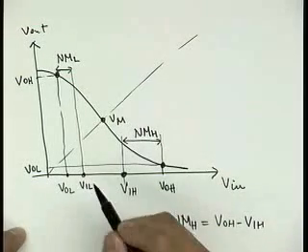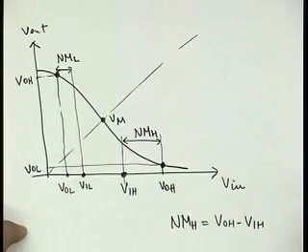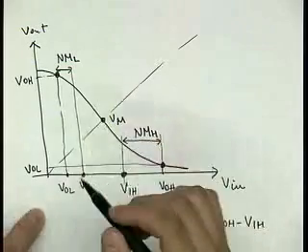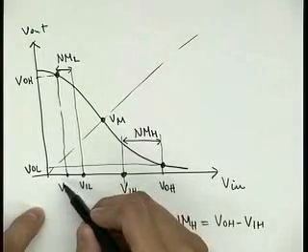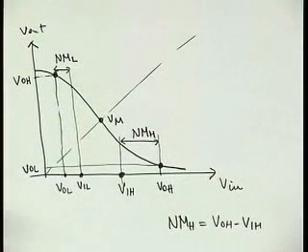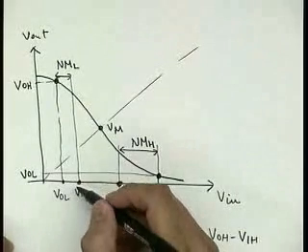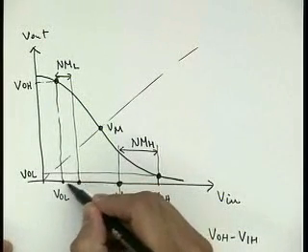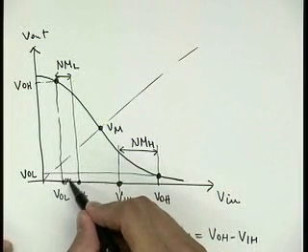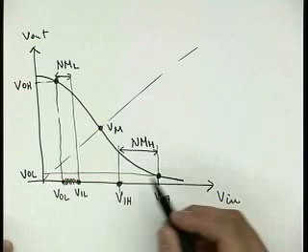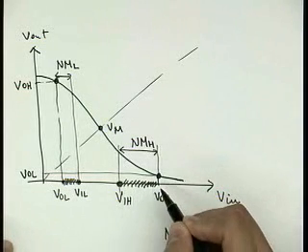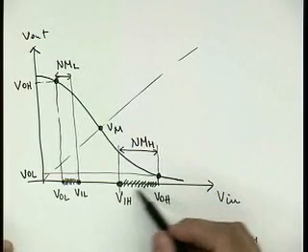So VIL. Basically that's important to understand, and that, for example, VOH is not a function of VIL, but rather VOL, simply because that's the way we introduce these terms. That's oftentimes confusing, but it's important to understand the definitions and just stick to them. Starting from this VOL, you have a certain region over which you can tolerate noise and still have logic 0 treated at the input, and also over here you have logic 1 with some noise.